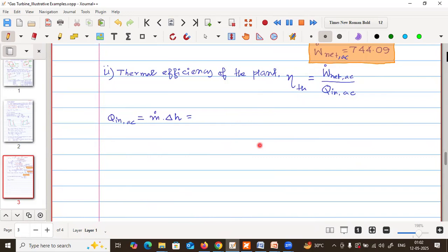Okay, just like steam power plants, these are all steady flow devices, and the corresponding work or heat, that means energy interactions, are related to enthalpy change. So whether it is a constant pressure process or not does not matter. That will be the change in enthalpy that comes from the first law. Okay, so there is m dot Cp for this heat input process, Cp for the combustion.